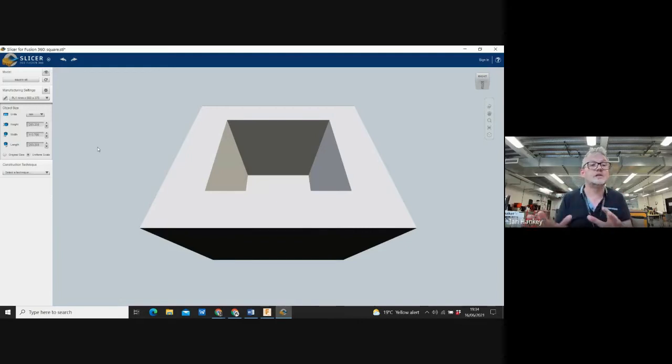If you wanted to change the size, it's exactly like Cura. We can make sure we've got uniform scale clicked here. I've just clicked it off. I'll put it back on again, and you can see uniform scale. I can change any of these sizes, and it really is quite important because we need to think about our material. What we don't want is a design that uses all of this and a tiny bit extra. You've gone onto another sheet. In actual fact, it's called nesting when we try and figure out the best way of putting all these shapes onto our material without too much waste. So we can change the scale of this quite dramatically, quite easily.